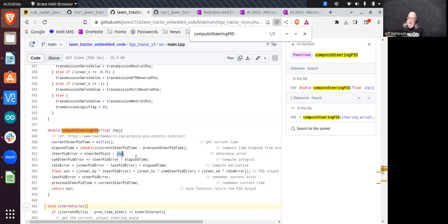So rather than looking into the PID stuff, it's just a matter of telling it. Consider this: if you pick up your joystick and you got the thing on the ground and driving forward, if you just slowly move your joystick right or left, your steering is going to follow that. Now, if you slam it all the way to the right, your PID is going to go, whoa, let's give it full power. It's going to slam over against the hard stop.